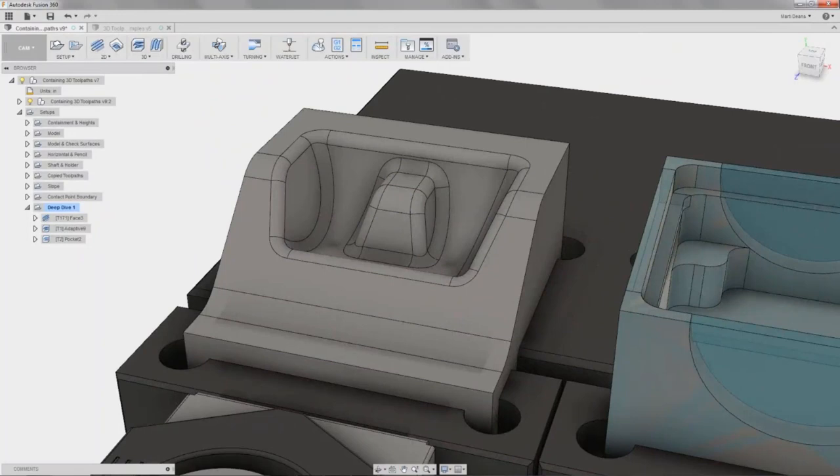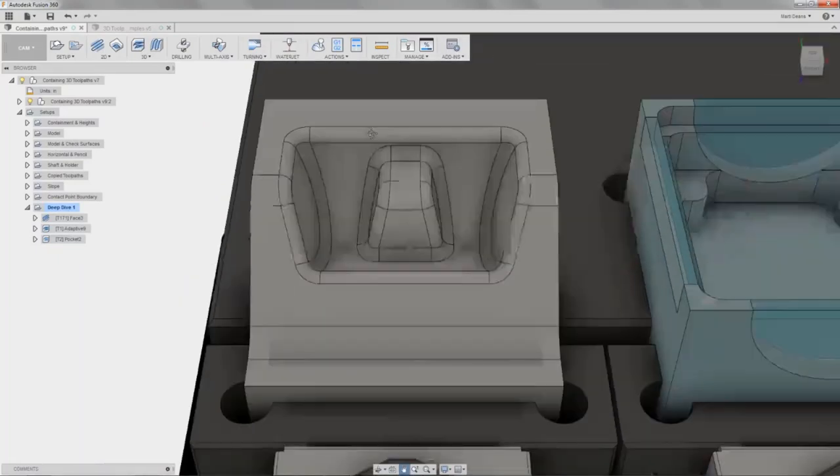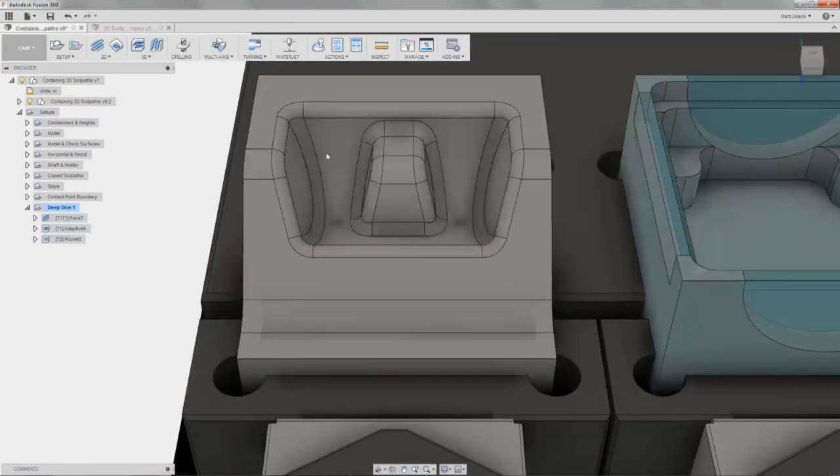So we're going to switch gears into finishing and into containment specifically. So for this part, I'm going to want to do a finishing operation to get this pocket all finished up. And if I look at it straight on, it looks like all these features here are running in approximately the same direction, but there are some draft faces, and draft faces are notoriously difficult.